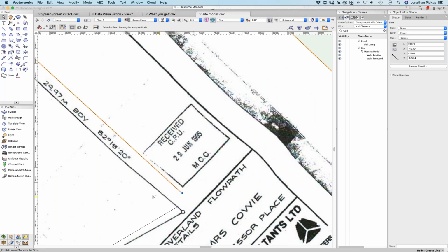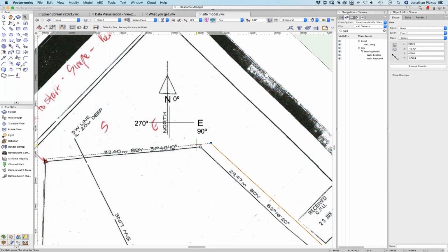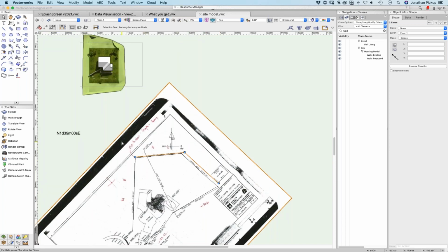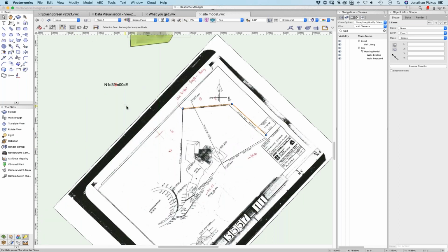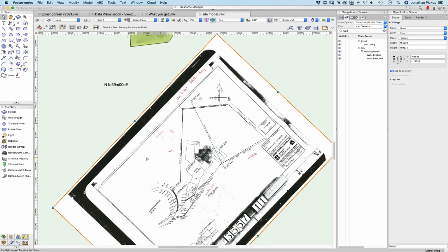So say we had a file that was working. Is the best way, when you get one of these old surveys, to work in the way that you're showing, creating these lines, rather than going into the property line and using the simple bearing approach? If it's easy, then use the simple bearings, which you can always go back to using this number system if you want. But as soon as you start getting a complicated one, it's easier to put the lines in. So for example, if we just get rid of this, let's just undo that. Let me just cut that PDF file.